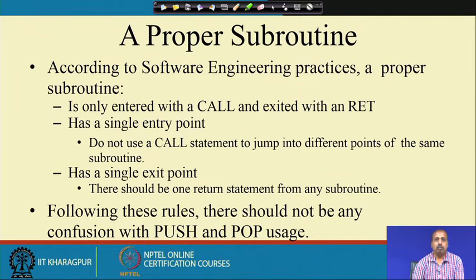Now, how to write a subroutine? What are the general guidelines for writing a subroutine? A proper subroutine is only entered with a call and exited with a RET instruction. So, it has a single entry point. Do not use a call statement to jump into different points of the same subroutine. What we mean is the guideline is like this.